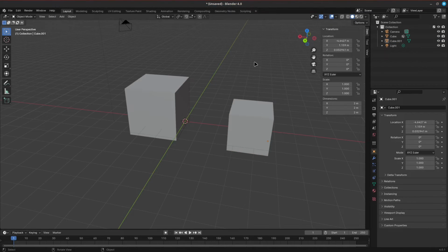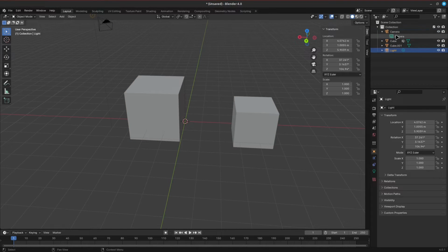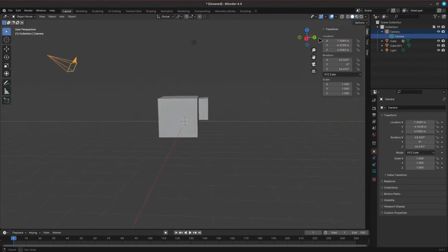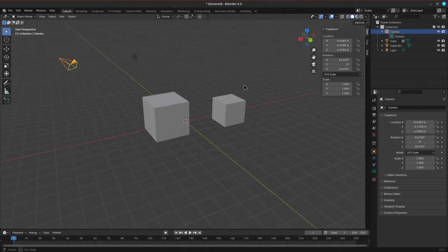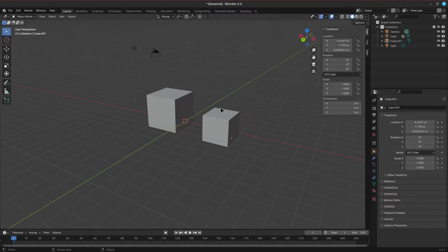Each Blender object type, mesh, light, curve, camera, etc., is composed from two parts, an object and object data, sometimes abbreviated to obdata. When referring to the object, we are really talking about the position, rotation, and size of a particular element. When referring to object data, that holds everything else. For example, meshes store geometry, material list, vertex groups, etc.